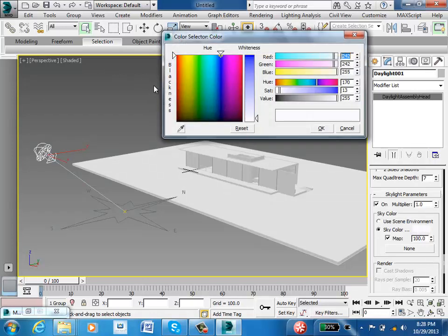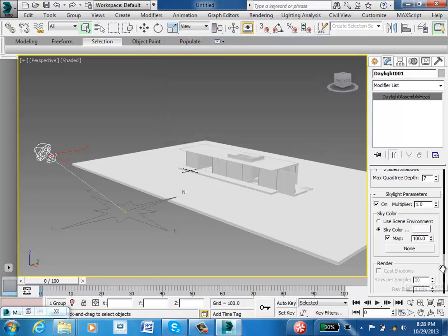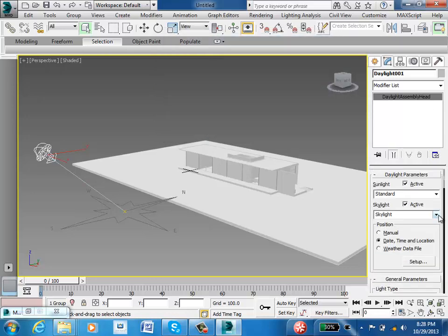So if you don't like that blue kind of diffuse lighting in your rendering, you can convert it into a standard light, which again, we'll do a little later, probably on Thursday when we get into interior light renderings. And you can then have much more control over the color of the sky, etc. For now, we're going to go back and change it to MR sky, MR sun, because our exposure control is based on that.